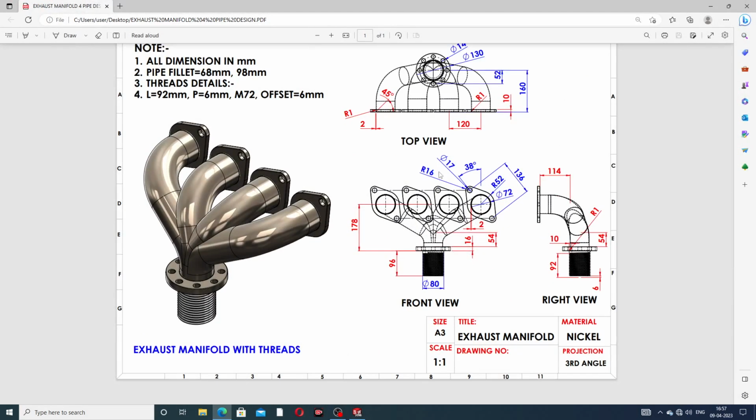And next, this circle is drawn here, and a pattern is also used here. This circle is big, with a diameter of 130 millimeter, and the center distance is 160 millimeter. Okay, and one point is very important: this point is 178 millimeter, and this direction is upward.